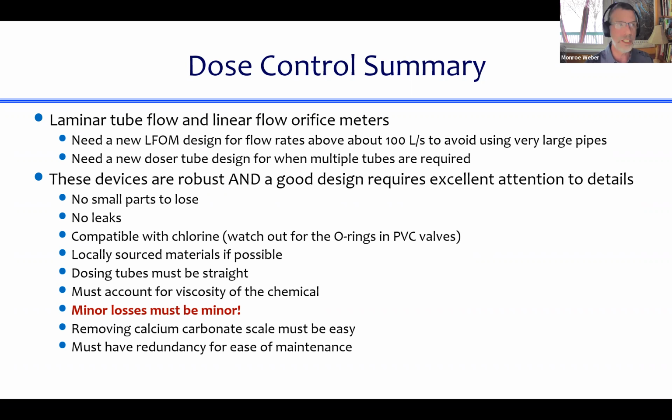And now you're wondering, why don't we just use bleach instead of calcium hypochlorite? The reason is that you can buy solid granular calcium hypochlorite, and the amount of chlorine per mass of calcium hypochlorite is much, much higher than the amount of chlorine per mass of bleach. So if you're thinking about transport, the cost of getting this chemical to your water treatment plant is lower if you can use calcium hypochlorite.